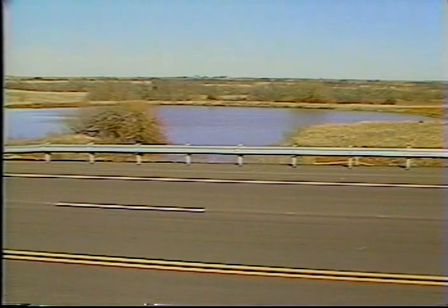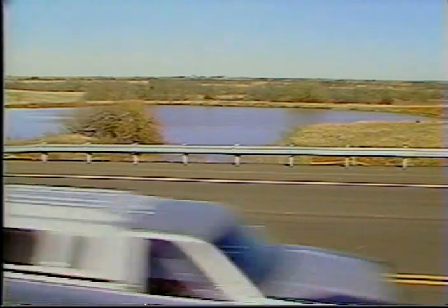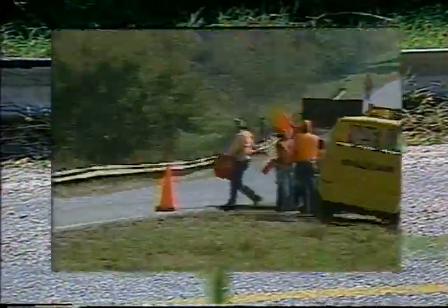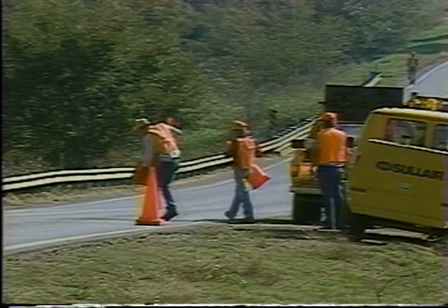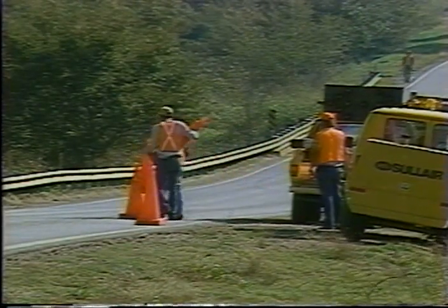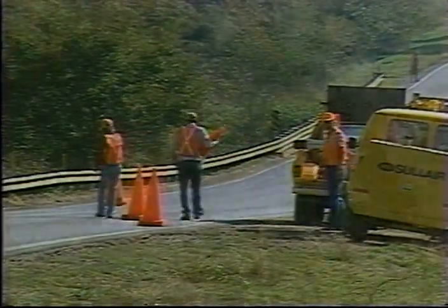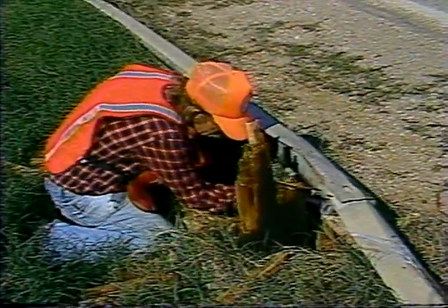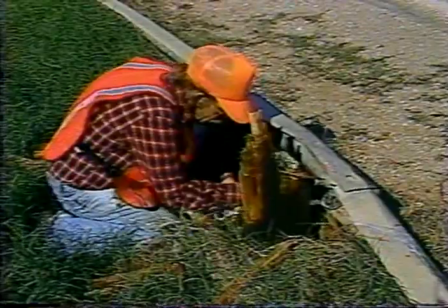The different systems around the country may vary, however, basic repairs are the same. The following repair crew demonstrates their technique on this W-beam strong post system that's done its job, and it's now up to them to put it back in service. Upon arrival at the worksite, the first order of business is to set up a traffic control safety zone. The crew begins the repair work by first loosening the connecting nuts and bolts of the damaged system.